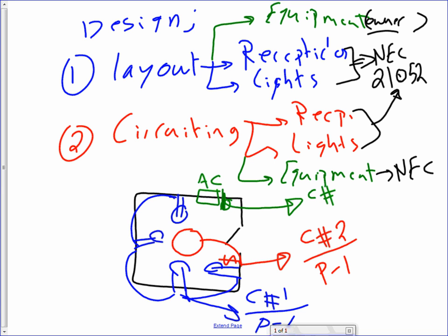In order to take a 240 circuit, what do you need to do? Either adjacent evens or adjacent odds. So you're going to take the 1, 3, or 2, 4. Or you take these two together. Any 2 adjacent, these, or these. Are you guys following with me? 2 adjacent odds or 2 adjacent evens to get you 240.